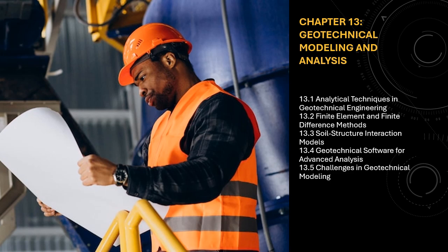The method helps predict the time-dependent settlement and pore pressure distribution in soils. Seepage analysis. FDM is used for groundwater flow and seepage analysis, particularly in the study of flow through porous media and determining the hydraulic conductivity and permeability of soils.